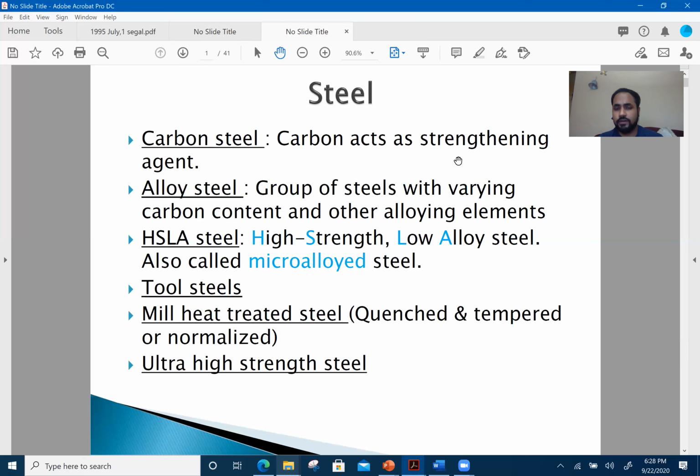Something that Dr. Aryave might be interested in is, if you're adding an alloy element, you want to look at the phase diagram of the material. Let's say you want to add aluminum. How much aluminum do you want to add? To get that information, you will have to look at the phase diagram of iron and aluminum. The best way to find a phase diagram is to go online. There are a bunch of databases present. I think ASM has a database.